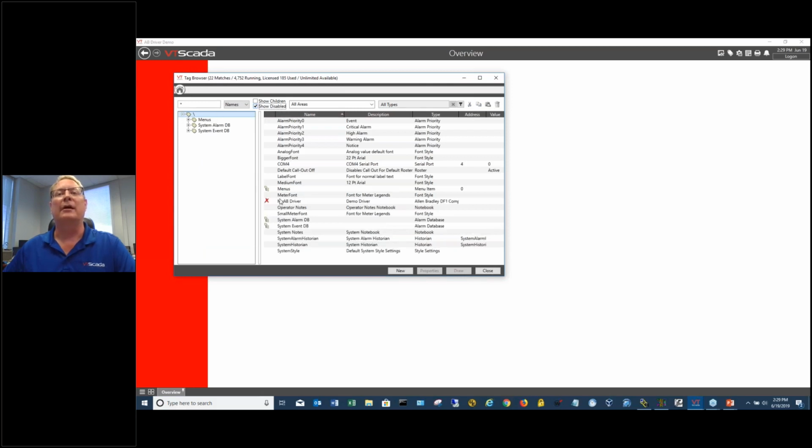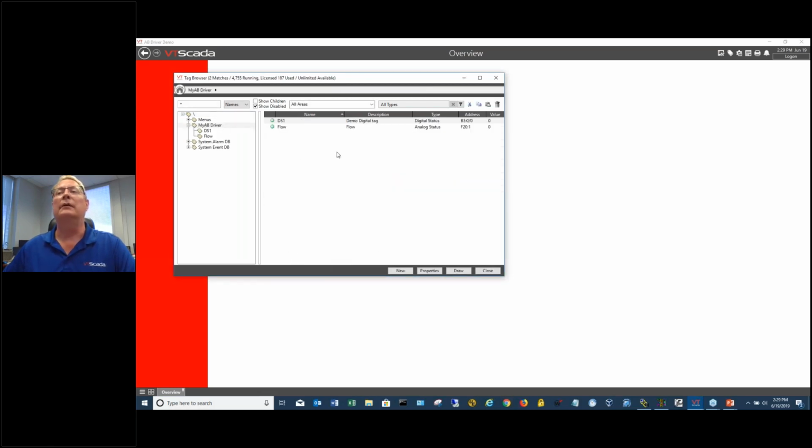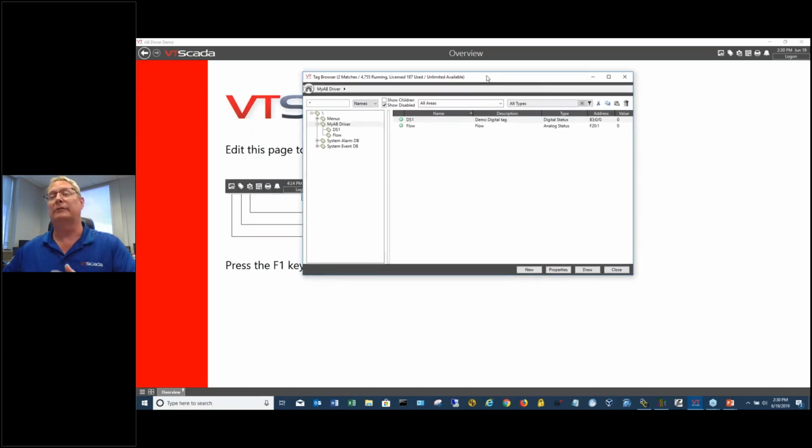Okay, so the Allen-Bradley driver tag has been completely disabled, and the child tags have also been disabled when I did that. So now I'm going to enable it again, and here we go. There are my tags, and you can see that I've got data coming in. Okay, now that's how you set it up for a serial connection. It's pretty simple.